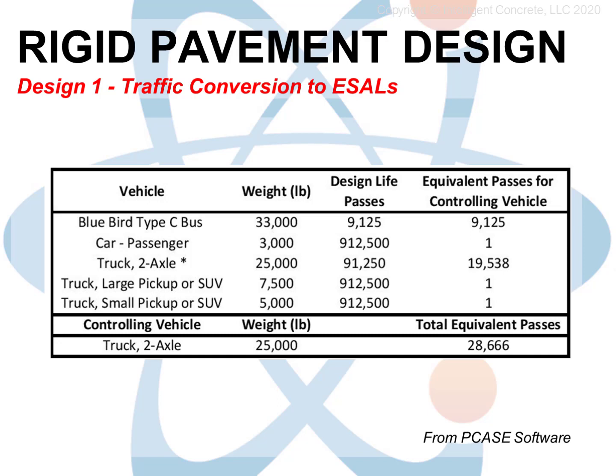Traffic is measured at various times of the year and from year to year, and that starts the process of forming the opinions on future traffic growth patterns. There's a lot of crystal ball voodoo in traffic predictions, and we're not going to dwell on it anymore today. A couple of terms here. Design life passes. That is the daily passes times 365 days times 25 years.